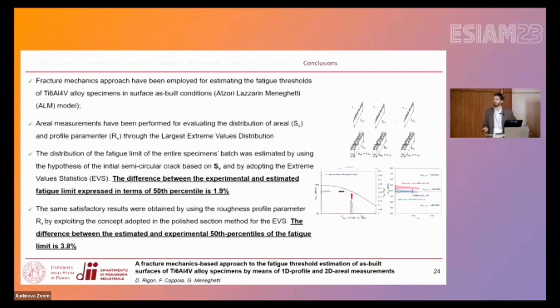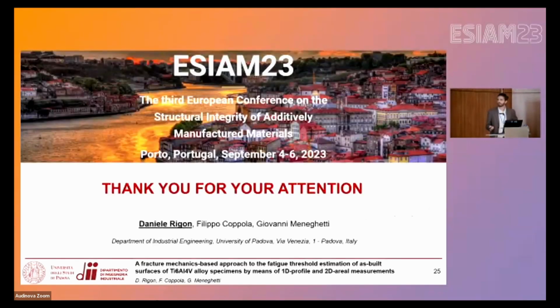So concluding, we applied the fracture mechanics approach for estimating the fatigue limits of as-built titanium alloy specimens. We defined a sort of compatibility for analyzing also the profile measurement of the roughness of as-built additively manufactured materials. And we see that our estimation of the fatigue limits is quite good compared with the experimental values obtained in our specimens. So I conclude. Thank you for the attention.